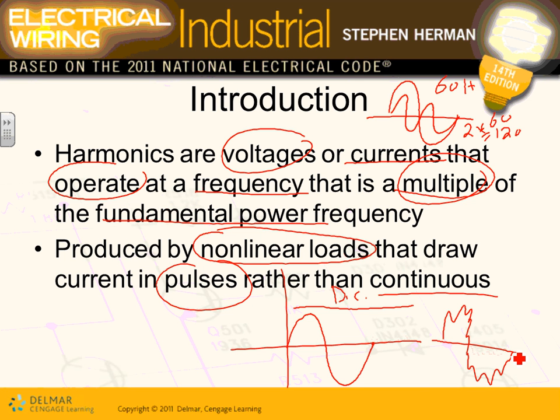And if you have PLCs, look at the PLCs. If you have VFDs, we were talking about VFDs. You know what VFDs do? Instead of giving the motors this signal to control the speed, they give them pulsation, guys, something like this. They give them multiple pulsations like this. Look at this: pulse, on, off, on, off. By doing this pulsation you can control the speed of the motor, beautiful, the VFD's advantage. But in the process, that creates a lot of distortion in the system, which means overheating the equipment. So who cares? We need to handle it, right? It's a necessary evil. It has to be there, but we need to handle it.